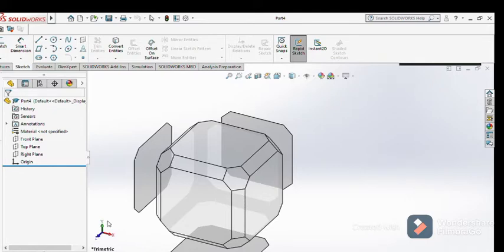As you look at the diagram, they give us our origin, and on the 3D they show us exactly where our origin is. By the looks of things, from the top view, the origin is in the back. On the front view, it tells you the origin is in the front, which the top view clearly states.